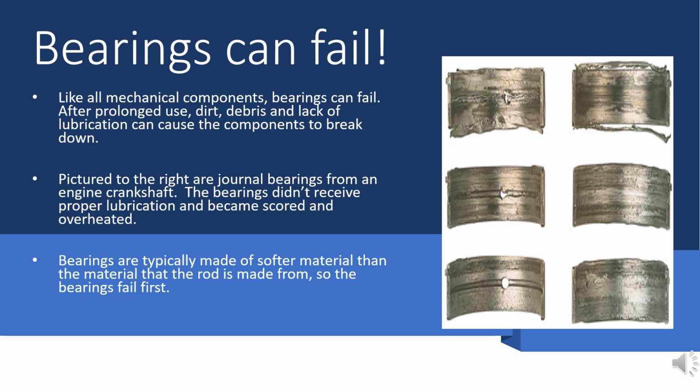Typically, damage like this would happen from either debris or dirt getting in between the bearing and the crankshaft, or the main cause would be it running out of oil. Lack of lubrication makes more friction, which causes more heat, and then the metal ends up melting.